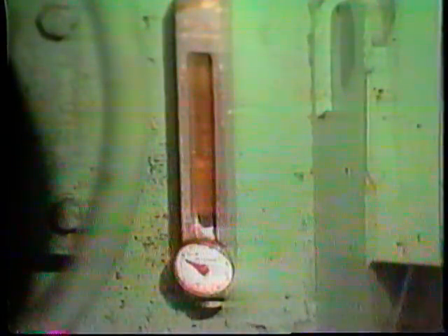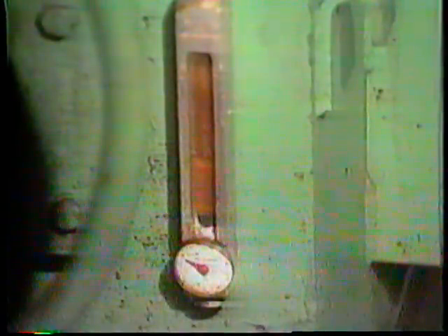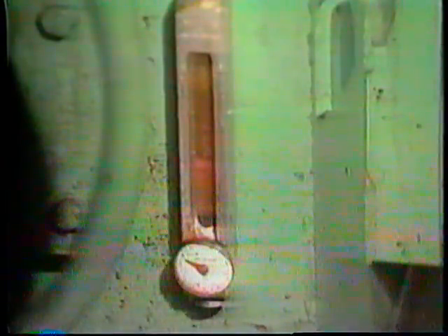Since the oil level will drop when the machine is running and may rise as the oil warms up and expands, manufacturers usually specify under what conditions the oil pressure and level should be checked. To make checking the reservoir easy, many reservoirs have a sight glass to indicate the proper level. Some sight glasses have two levels marked, one for when the machine is running and the other for when the machine is at rest. Be sure to read the proper mark when checking oil levels.